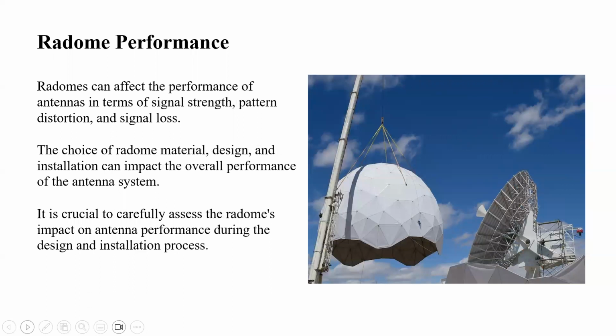So now let's see what the radome performance is. How do radomes perform after being installed? Radomes can affect the performance of antennas in terms of signal strength, pattern distortion, and signal loss. The choice of radome material, design, and installation can impact the overall performance of the antenna system. It is crucial to carefully assess the radome's impact on antenna performance during the design and installation process.